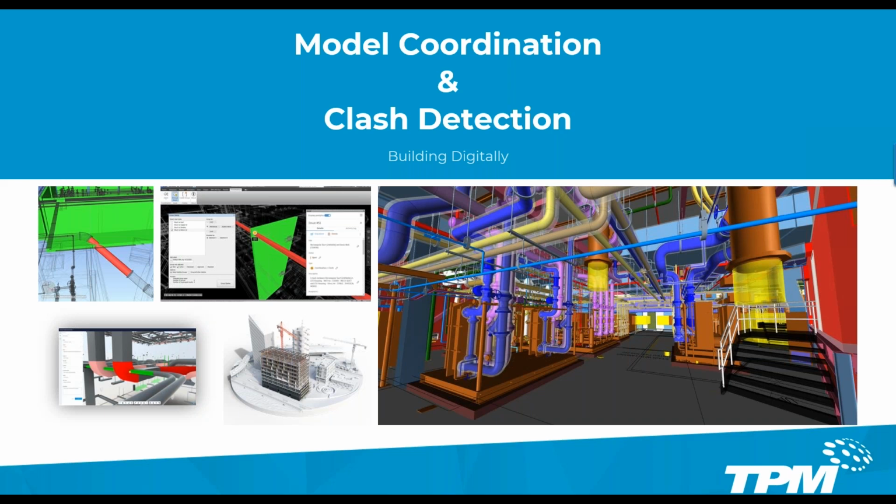So we can't coordinate what we don't have or what we couldn't build based on the drawings and other information we have. So it's important that we have complete information so we can build that building digitally. And then once we do, we're able to run that clash analysis and produce quite a few different reports. And you'll see some green and red photos over here highlighting clashes where we have a piece of pipe running into a steel member or a piece of pipe running into some duct elbows. And that identifies where we need to adjust our systems accordingly.